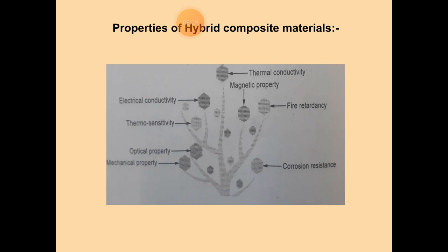Novel composite materials have been developed: fiber metal laminate, which is FML. It consists of metal sheets, which can be aluminum, steel, titanium, magnesium, etc. The composite consists of alternate layers of PMC and metal sheet. The nomenclature scheme goes in various ways, such as glass fiber reinforced laminate and aramid fiber reinforced aluminum laminates.